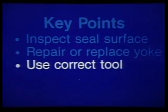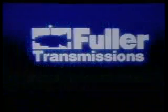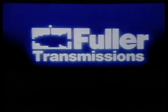Use the correct installation tool when installing a new seal. Use caution when installing the yoke on the transmission. Inspect the seal after yoke installation to be sure that no portion of the lip has rolled back. Today, alternatives are available when repairing a transmission leakage complaint that, if used, can make the system better than new. Take advantage of this new technology to get the most out of your Fuller transmission.